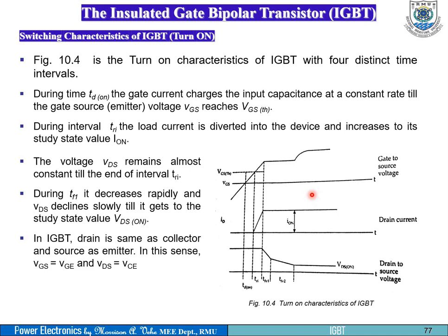Okay, so during that, as VGS goes to VGS threshold, look at where the current is. The current is actually 0. So when you get to the threshold value, before it will start conducting, until we exceed a certain value of the threshold, we cannot rise to a steady state value of the drain current. So that is what is happening here.